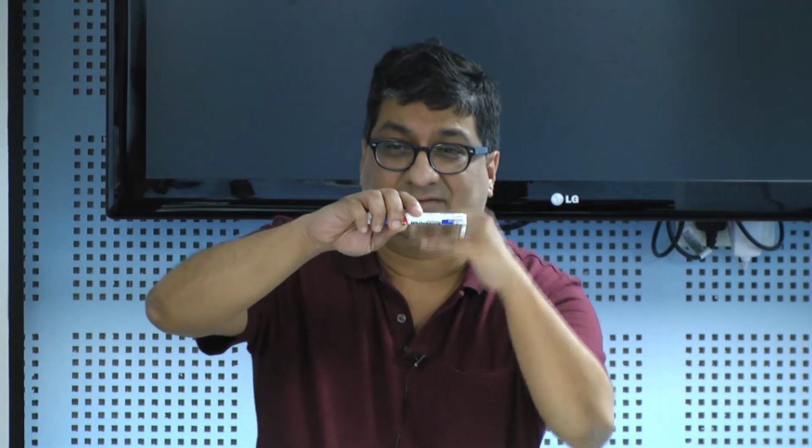When that's happening, if the water is moving very fast, the solute may not have enough time to go from the bulk solution to the surface and then cross over to the other side of the interface. So it creates what are called mass transfer limitations. If you're running columns where you want to do mass transfer and get rid of something, you want to run it at some fairly slow speed. If you run it too fast, you won't have enough mass transfer. So chemical engineers worry a lot about keeping the reactors slow for the reaction to take place, but at the same time, if the reaction runs slow, they're making less of a product, which means less of a profit.